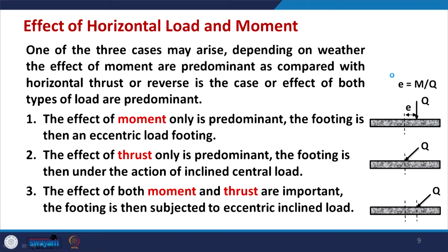If you do not have the moment, you could assume that your vertical load Q is concentric, acting at the center. However, when the moment is there, it can be considered that the vertical load is not acting at the center, but at some distance from the center, and that is called eccentricity E, which you could see in this case.